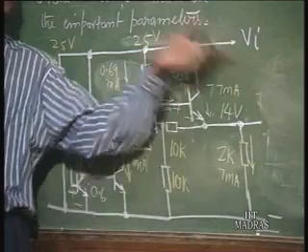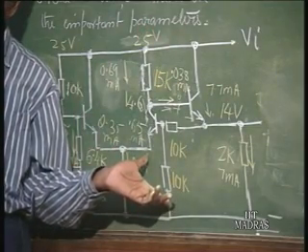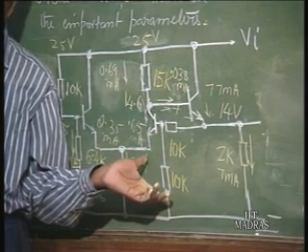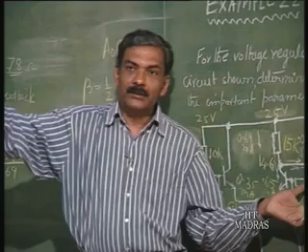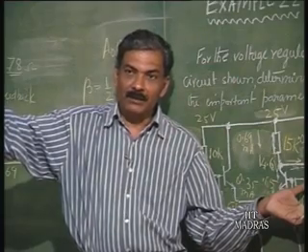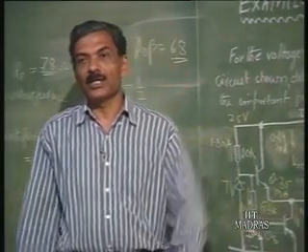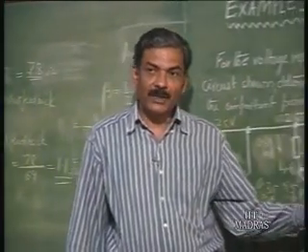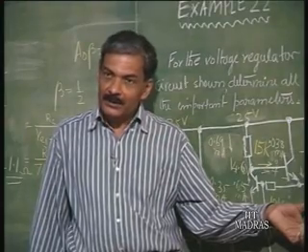This is functioning at low frequency, this is a DC regulator, and therefore output impedance, on the other hand, is important only looking at this circuit from the circuit that is using this as a power supply. That circuit may be working as an oscillator at, let us say, 1 megahertz, then you have to evaluate the output impedance at 1 megahertz for this circuit. That may not be purely resistive.